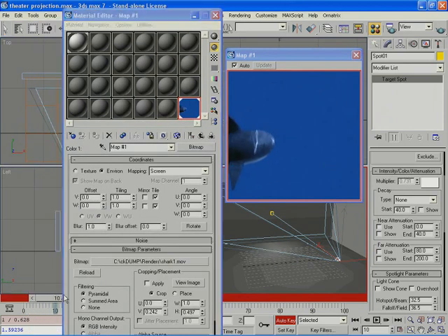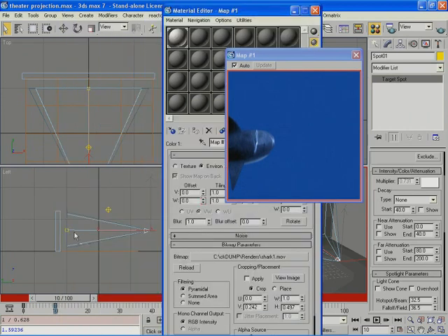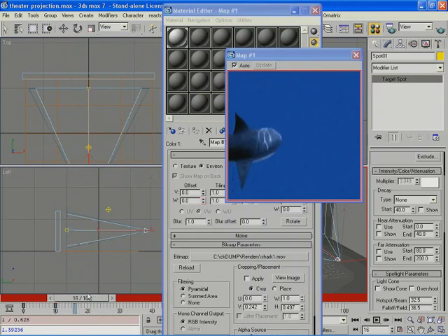So at 10, I have a keyframe. I'm going to make the rolling happen, let's say, by 20, I want it to have rolled twice. So I'm going to set the W value to 2. So now if I scrub, it's going to roll twice between 10 and 20 because I set the value to 2. If I set it to 1, it would roll only once.